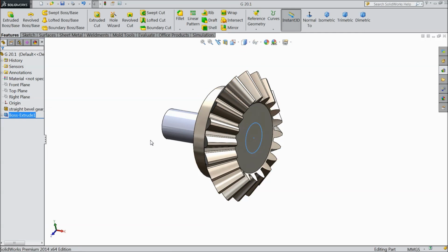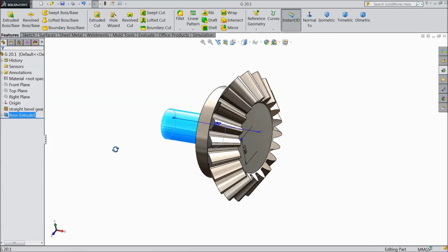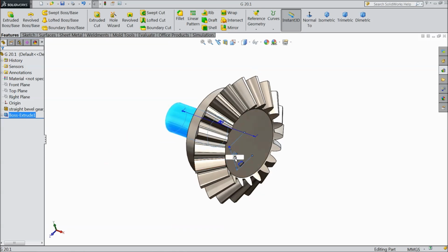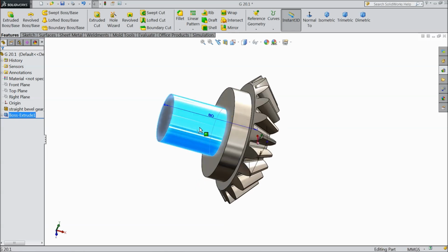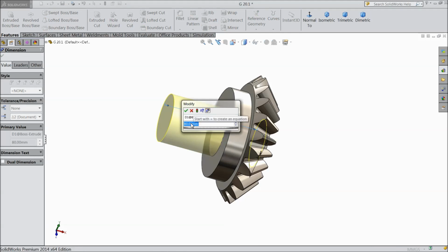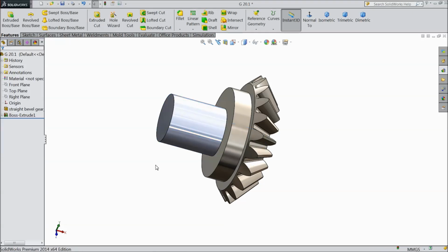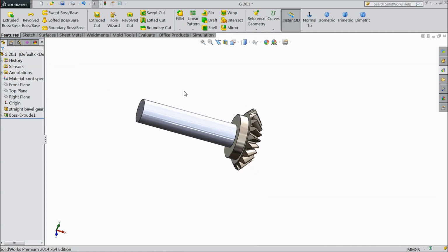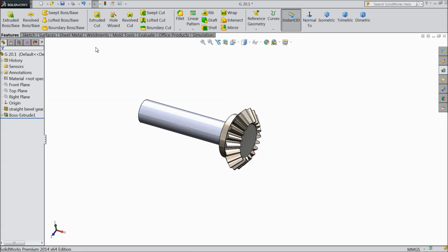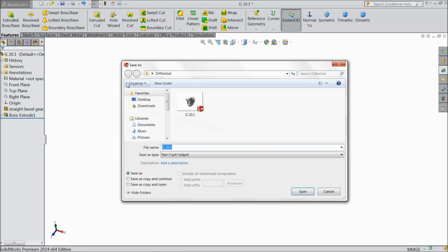We will do it later. Now select this body, select this diameter and set it to 40. See, it becomes 40. Again select this, and this height, length keep, let's say, 200. Select, refresh. Now it's 200. Now save as G20.2. This is the second gear.